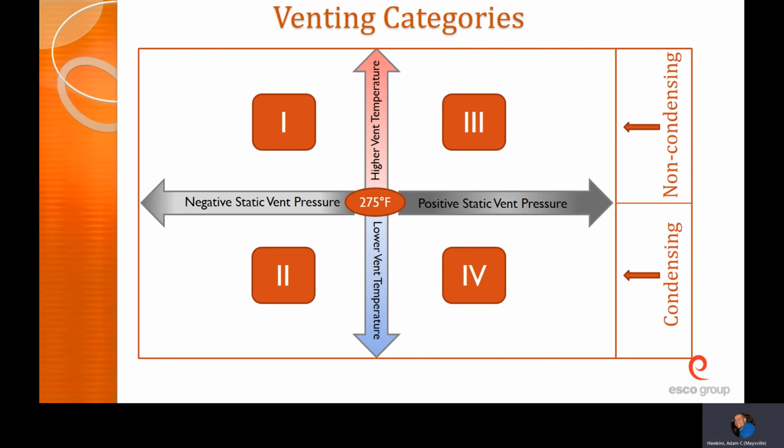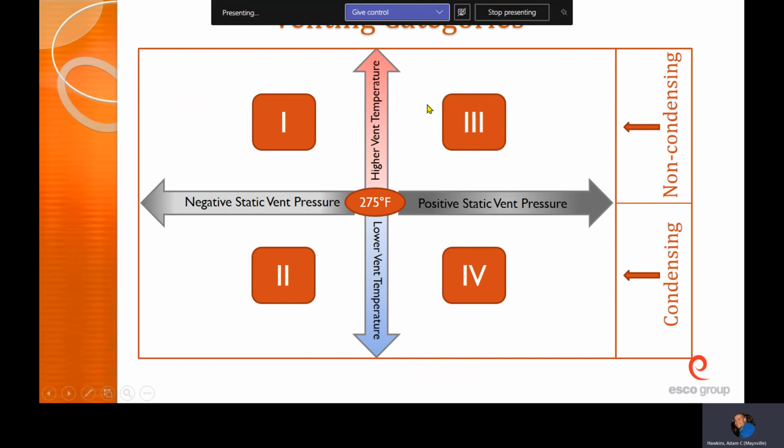All right, so different categories of venting, as we've already talked a little bit: high efficiency versus standard efficiency, non-condensing versus condensing gas furnaces. So condensing gas furnaces are trying to remove as much heat from that flue gas as possible before they send it outside. As a result, you're going to run a much lower vent temp. So a high efficiency 90 plus furnace, the easy way to tell is you're going to have PVC pipe running out, or you should have PVC pipe running out the vent.